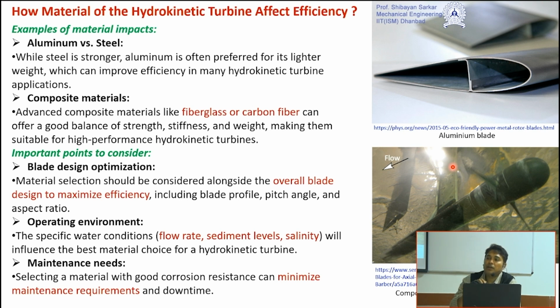Say your fluid velocity is the same, but the shape of the sediment is different. One is round, another has some sphere sort of shape. The sphere sort of shape sediment, with the same velocity, when it impacts the blade, will cause more abrasion on this particular blade.